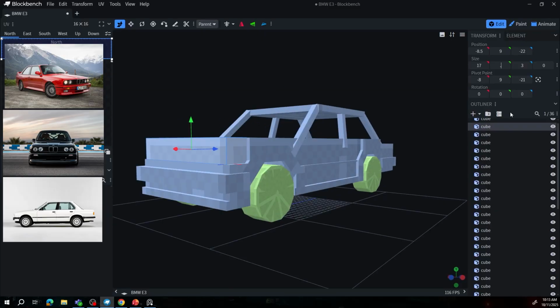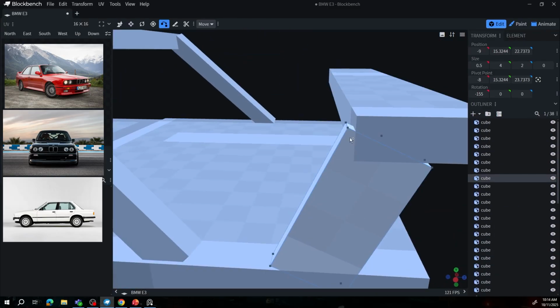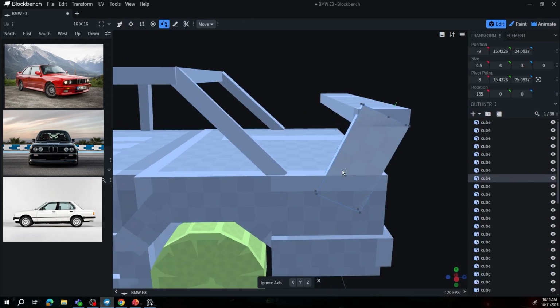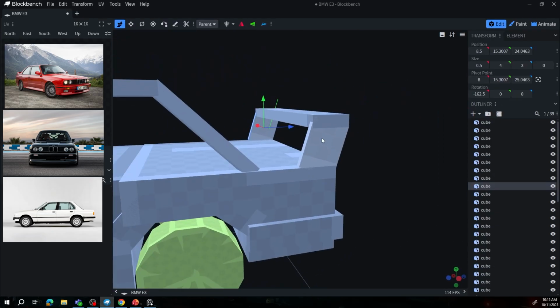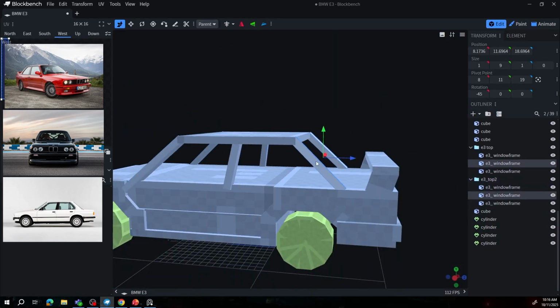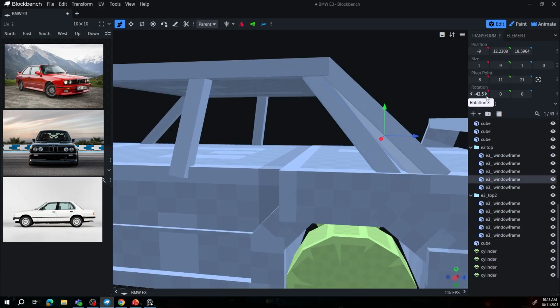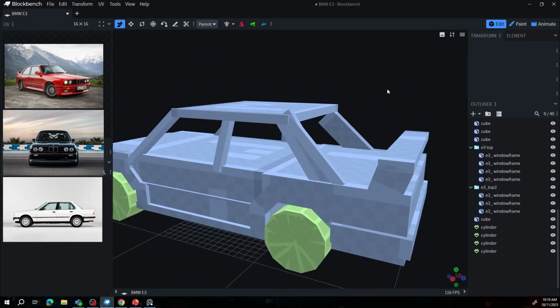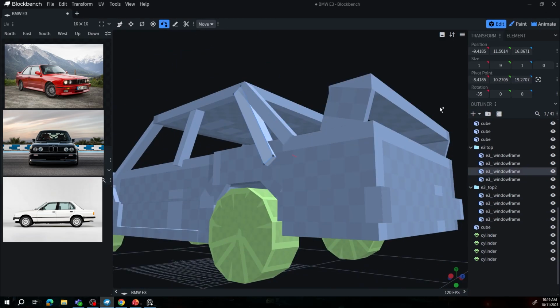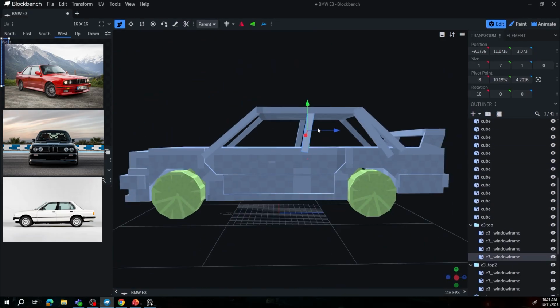A very useful technique I found when learning Blockbench was being able to inflate or deflate blocks by very, very small numbers like 0.0001 or minus 0.999. So A, the geometry isn't intersecting and it doesn't appear all jittery, and B, when you're texturing you can choose what piece is layered on the top, so you can paint the details on that piece.